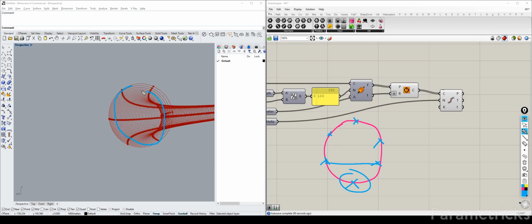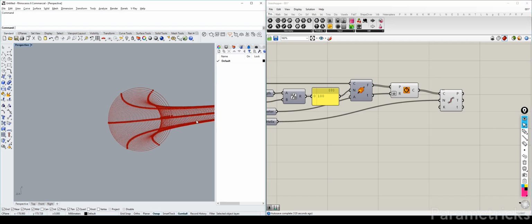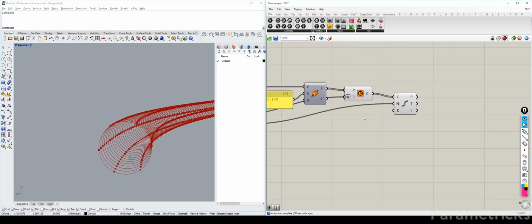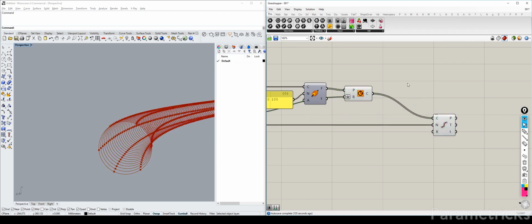That's not a good drawing. What I'm trying to say is that the deck is not that high. The deck is actually somewhere here, right? But the way our circle is now divided, the seam doesn't allow us to have 2 points here and 1 point at the bottom. So I have to rotate all these to the right direction. One way we can do that is to move the seam of this circle. So let's just do that. We type in move seam.